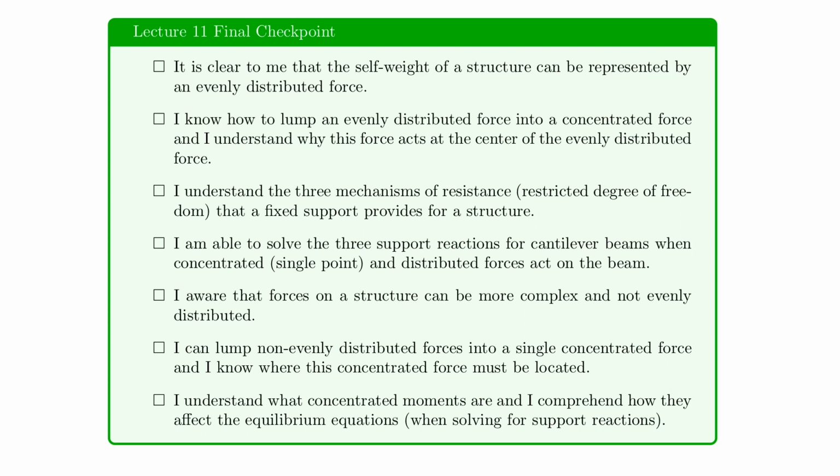So first of all, it should help you to understand what self-weight of a structure really is and how you can represent that by evenly distributed forces. So please make sure that that is clearly understood. Then you learned with the evenly distributed forces that you can actually lump a force into a single concentrated force, at least conceptually, so that you can apply this force at the center of the evenly distributed force for your calculations. So that should also be clear, and I think that was taught throughout this lecture.